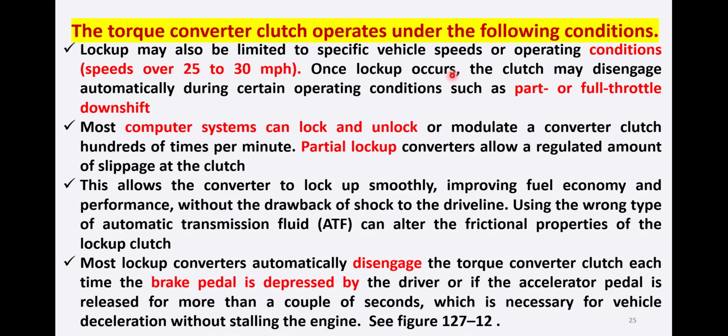Once lockup occurs, the clutch may disengage automatically during certain operating conditions, such as part throttle or full throttle downshift.